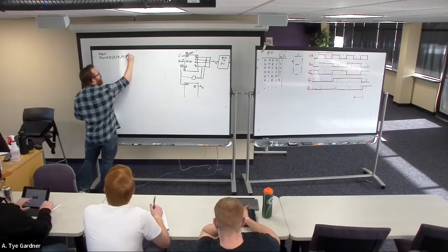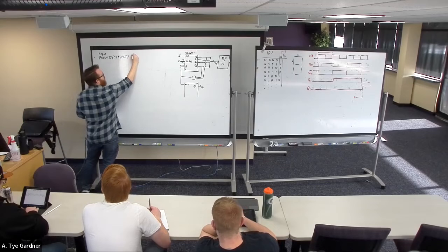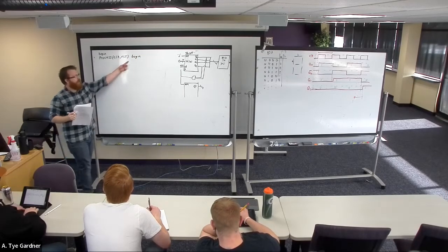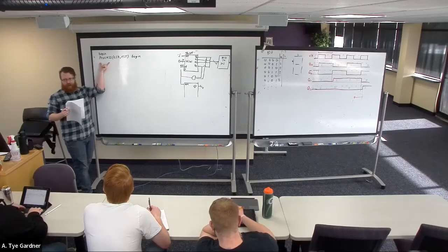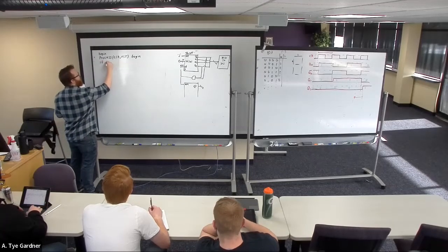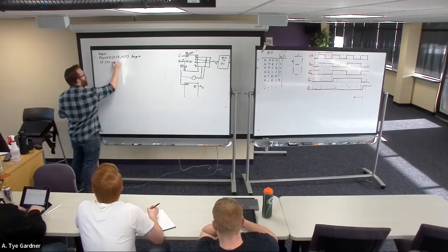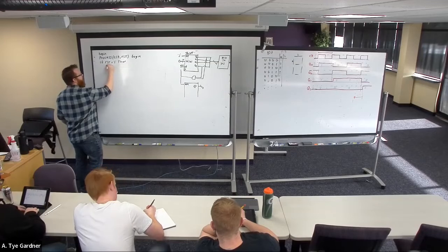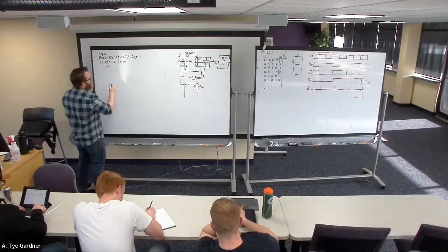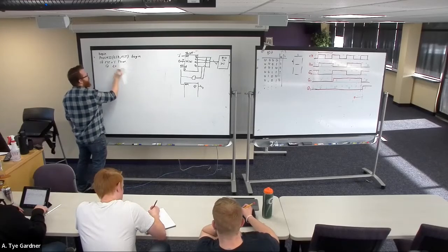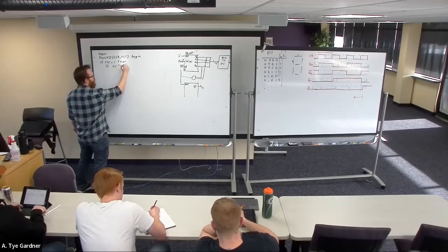There is a begin. It turns out on this board, it's going to be easier for me to put it over here. It's totally allowed. You can actually just begin as part of that same line. I tend to format it down here when I write the code in VHDL just because it's easier to read for me, but this is perfectly allowed. Then we say if reset equals 1, then our Q output gets assigned to, and I'm going to leave a little bit of space here after the Q on purpose, and we're going to come back to this later, gets assigned to 0, 0, 0, 0.